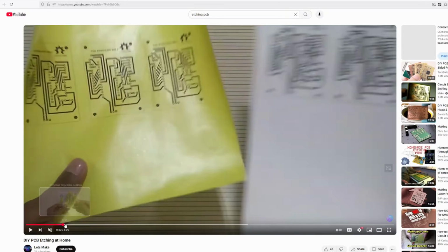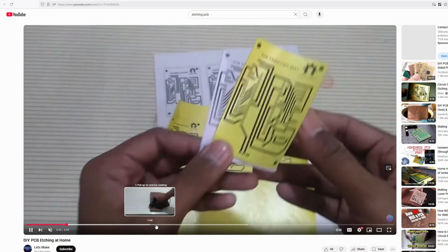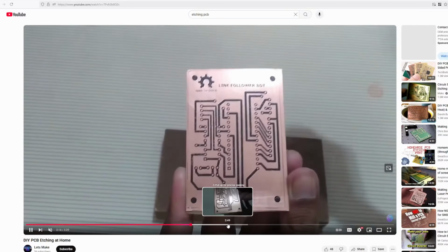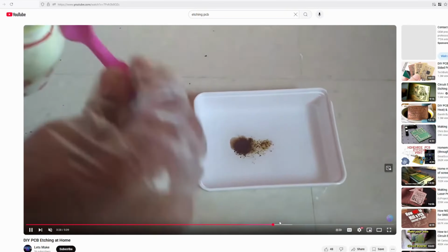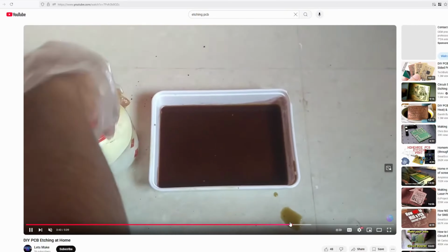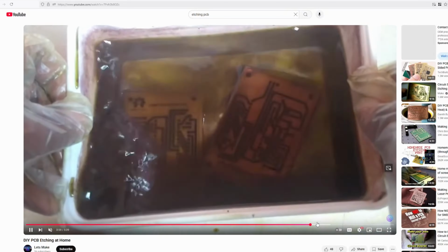The way most PCBs are manufactured is pretty straightforward. You coat the PCB with something that will prevent certain parts of the PCB from being etched. Then you dip it into something that'll eat the copper away, and it'll selectively only eat certain parts of the copper away. When you're done, you're left with a bunch of wires that are attached to some kind of substrate.